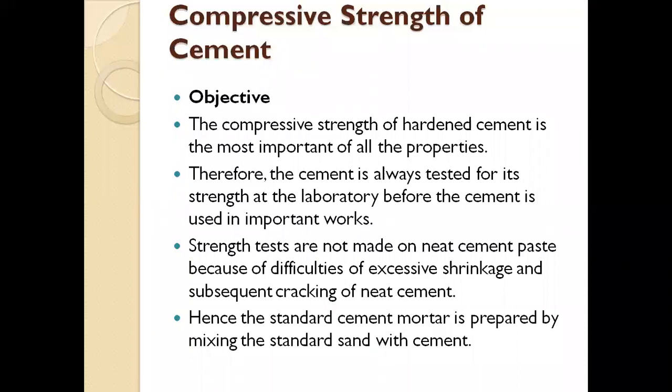Next, strength tests are not made on the neat cement paste, that is, on a pure cement paste, because of difficulties of excessive shrinkage and subsequent cracking of the neat cement. Neat cement means one in which we add only cement and water. If we take cement and water only, there is shrinkage, and it is not possible to cast and test a cube prepared with cement and water only.